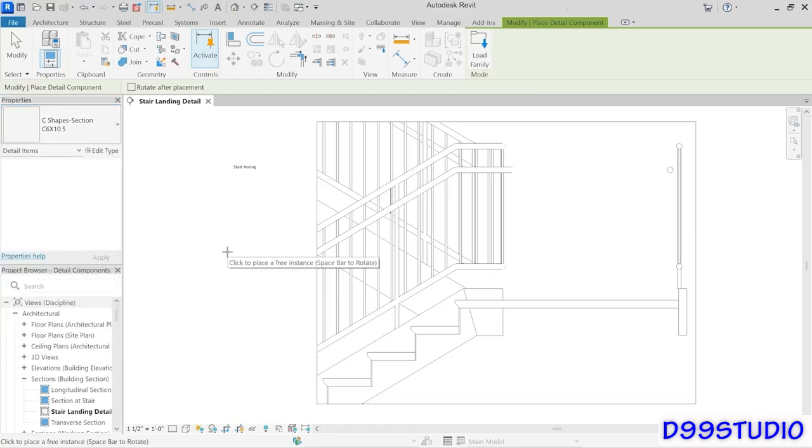And it won't appear out here because even though it's a 2D view specific element, it's still considered part of the model. So you need to move into the model view and place it somewhere. And I'm just going to place it slightly overlapping that stair stringer right there. It's not important that you get it precise, just place it roughly on screen for now.